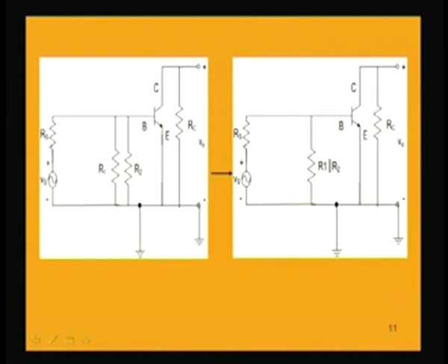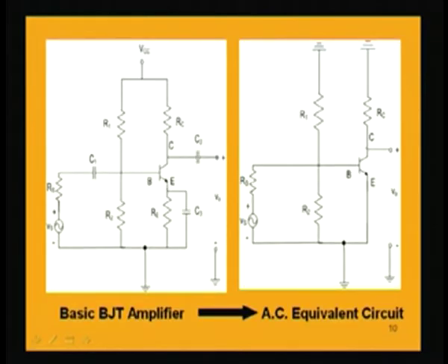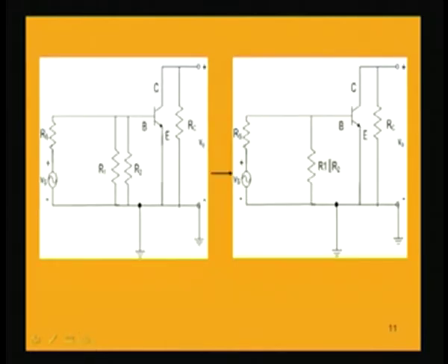Also this RC, if we look back, is grounded from the collector, but most commonly it is not drawn upwards; ground is always shown downwards. That is why, conventionally, we draw it again by connecting the collector through resistance RC to ground, and this point is ground. So, this is the conventional circuit which we have derived from the transistor amplifier and which is applicable under AC. The AC equivalent circuit is this one.